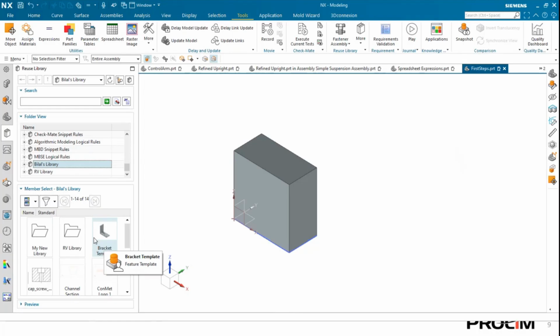the pattern and the hole size. Well, you can use part families to automatically change that, very easily and efficiently. And part families will pull in all the attributes of your model that you can then change. Now, you do need to give it a name, and you do need to give it a part number. You can give it whatever you want, but those are two values that must be in there.